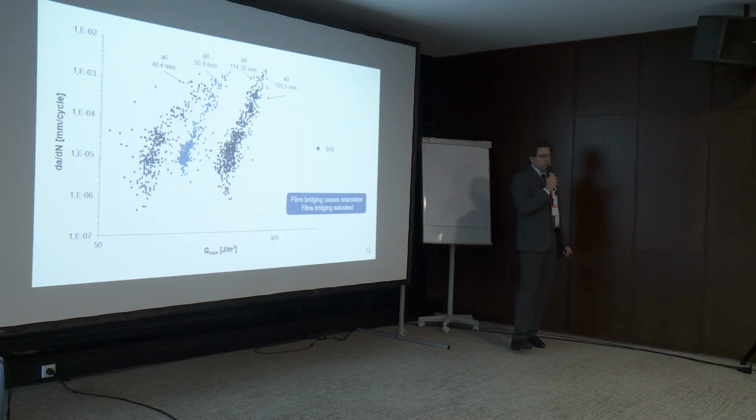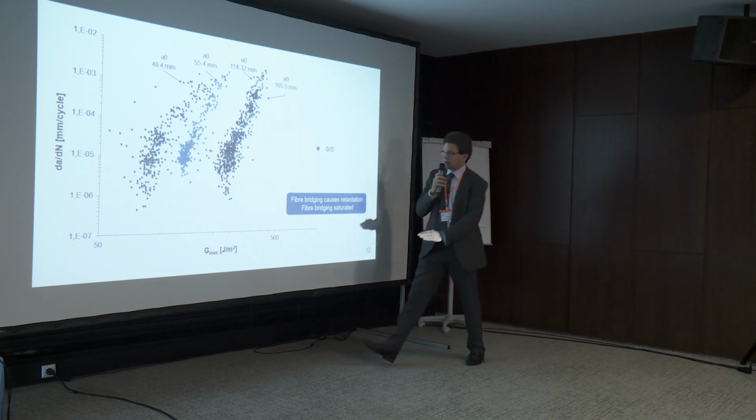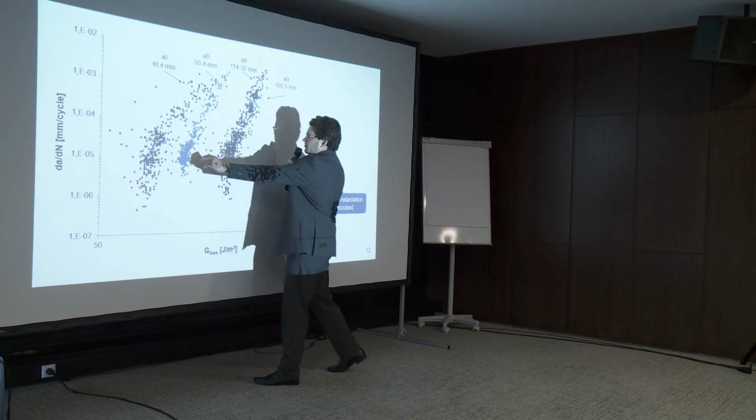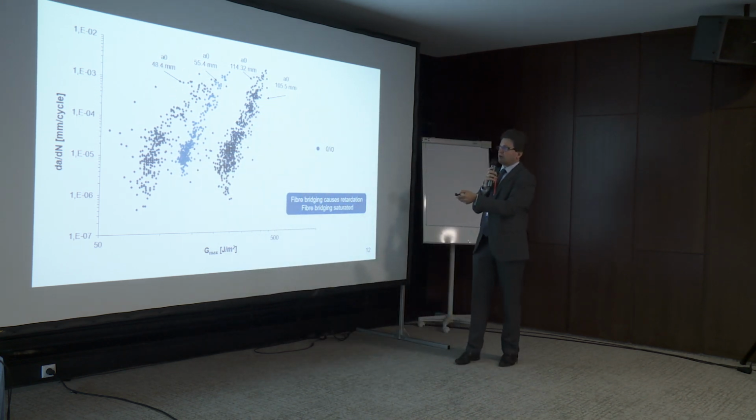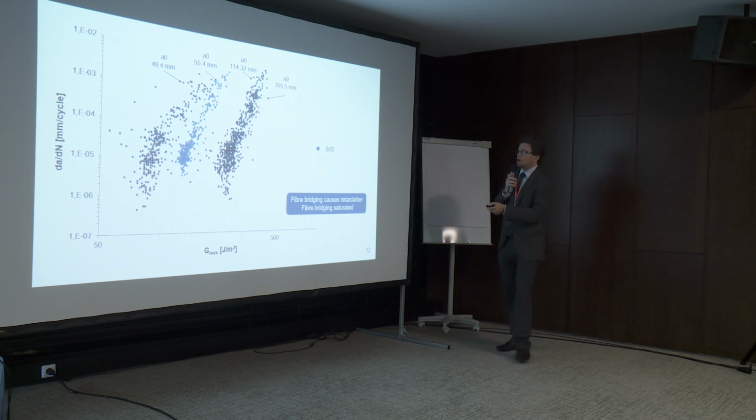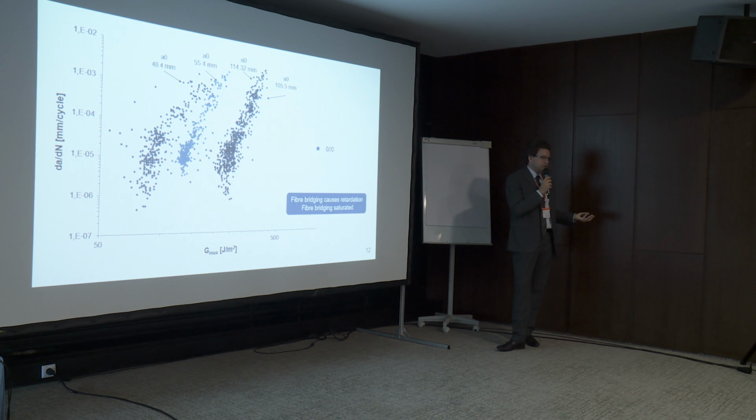This is for the 0,0 case. What we see is on the left here, the 2 short pre-crack tests, on the right the long pre-crack tests. And as we would expect, there's also a difference here for the short pre-crack tests in the crack length, and the curve shifts to the right for the longer pre-crack length. Whereas if we have a really long pre-crack, then we see the pre-crack length no longer affects the results, the curves are on top of each other, so we have a saturated fiber bridging behavior, is at least our interpretation.